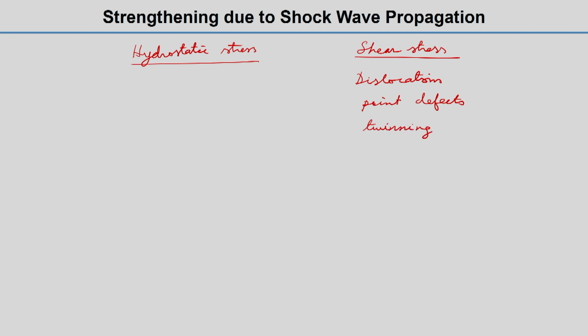So, shear stress is responsible for most of these defects, and then hydrostatic stress can be related to stacking fault energy. That means stacking fault energy is influenced by the hydrostatic stress, and then second phase particles.